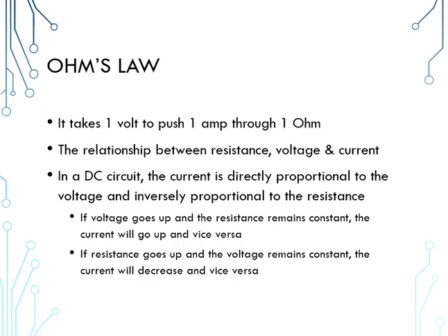The reason these relationships are so important is they can save us a lot of time, save us from having to do the math if you're a technician. They can give us clues as to what to look for, where to look on a circuit that is having a problem. So we'll use a light circuit for example. If our light is actually lighting but it's not as bright as it should be, we know we're not doing as much work as we should be, so our power, our wattage, is low. Our voltage and our current, we multiply those, that will give our wattage.